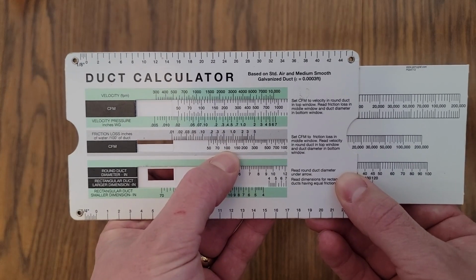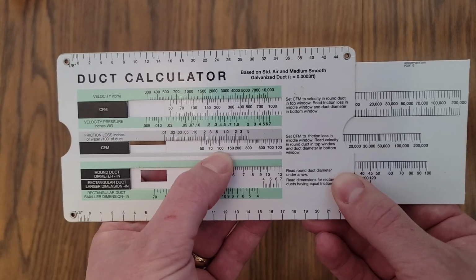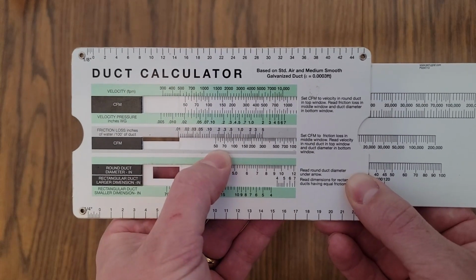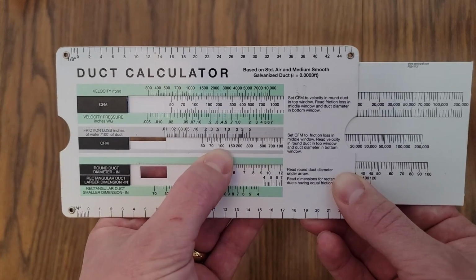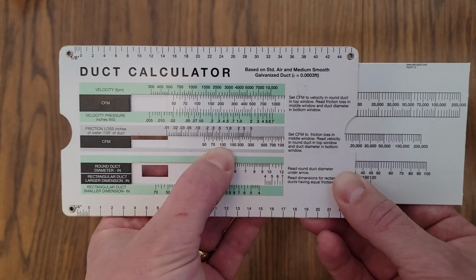What 100 CFM represents is the amount of air that is going to be pulled out from underneath the basement slab. If you have a smaller basement, you can go with a smaller CFM. Pulling 100 CFM out from underneath the basement slab, I think that's fine.